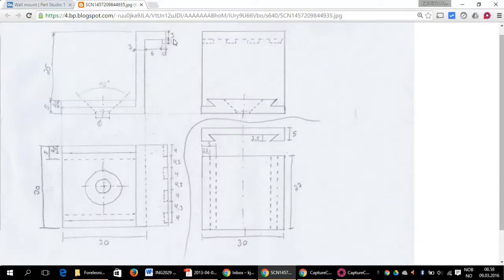In my original sketch here, I've done 3 millimeters down there. This means that I only exactly make these teeth enter. But what I'm going to do now is increase this one to 4 millimeters, because then we're putting a bit of strain on all of this. When I screw the screws into the wall, then everything here is going to be a bit under strain.